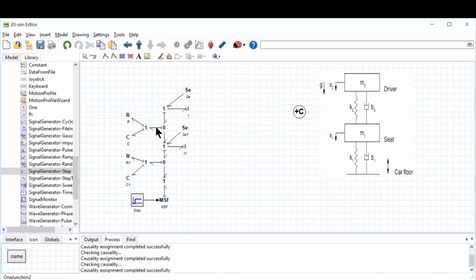So this velocity is coming from where? It's coming from this one minus this one, because we know that zero junction is an effort equalizer. So effort doesn't play any role here. So this is the flow coming to this junction minus the flow going out of this junction, which is transferred to this. So this is very obvious if you write the power balance for this zero junction,